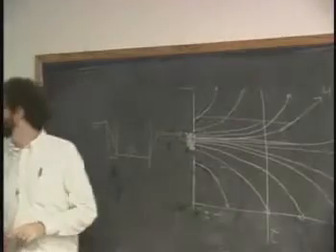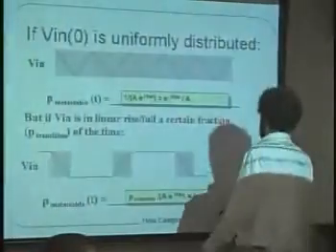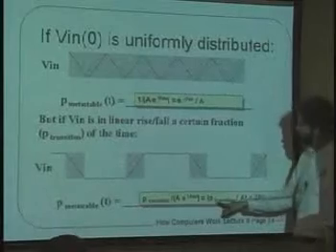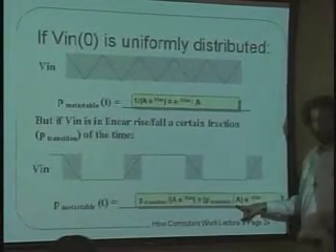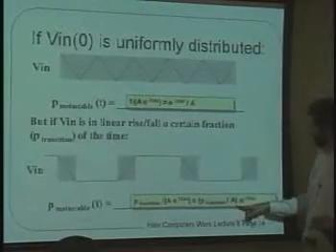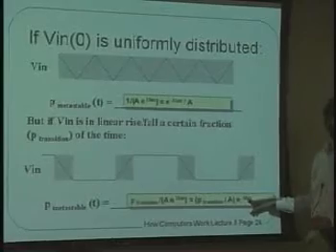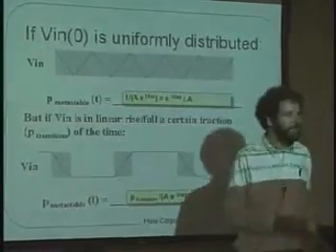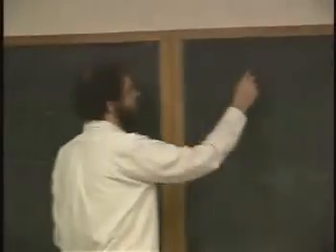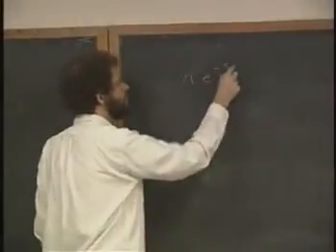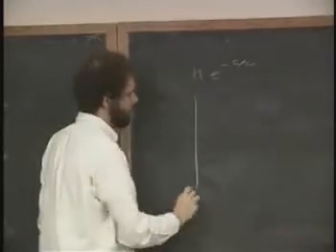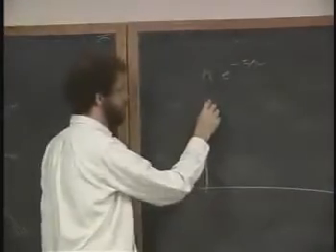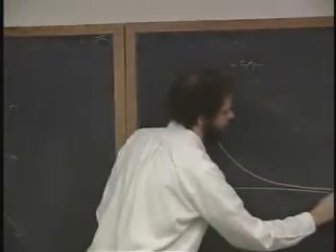Okay? And so, in summary, what you get is the probability that you are metastable is P transition divided by this amplification A of the feedback times e to the minus t over tau, because it's on the bottom over here. So e to the minus t over tau. What does that look like? Anybody know what that looks like? So some constant k e to the minus t over tau. It's not plotted to the x-axis. So it kind of looks like that.